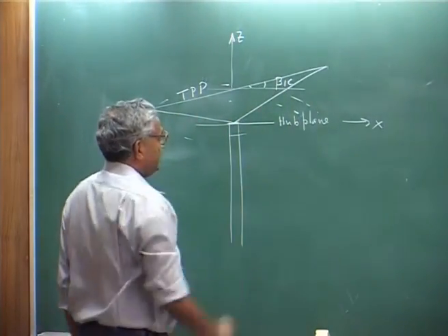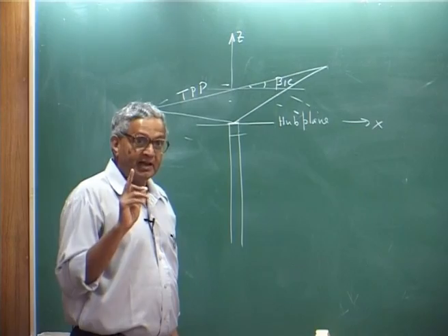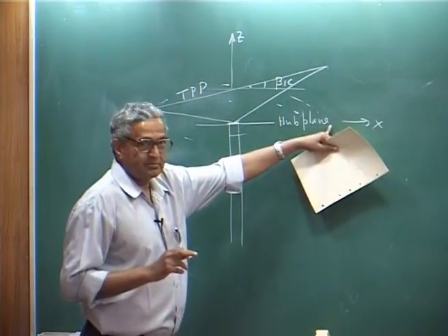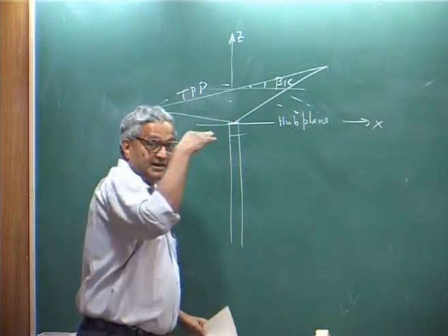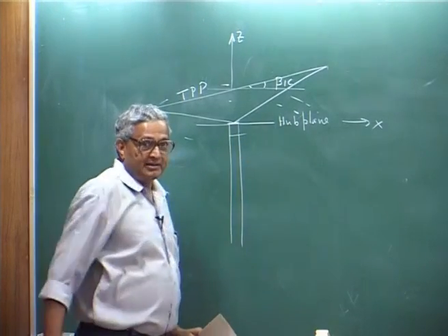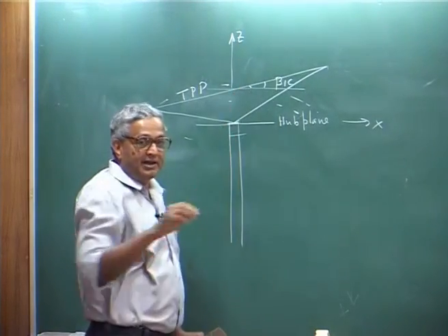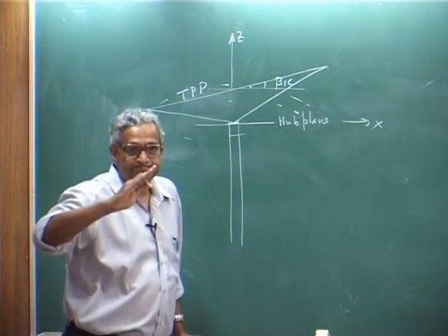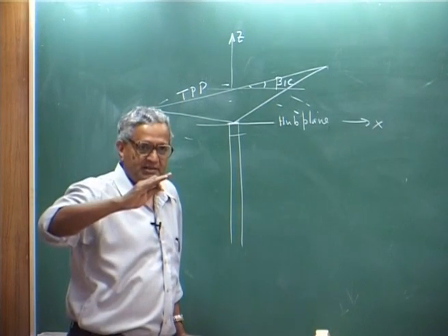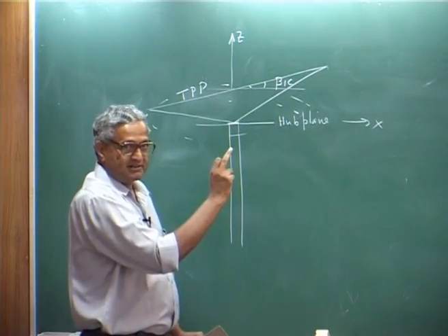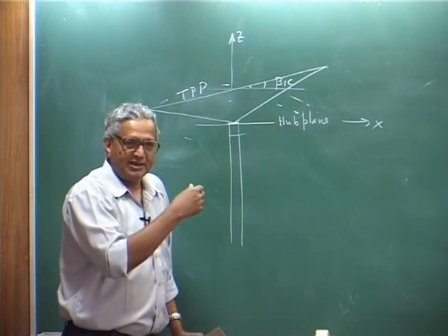No feathering plane means I am giving a theta 1s, because in this I am looking at it this way, in this y direction. The pitch angle I give when the blade is at 90 degree, I give a theta 1s which is positive. You assume that you are giving a positive pitch angle, and then when it comes to 270 you give minus, because sin 270 is negative.